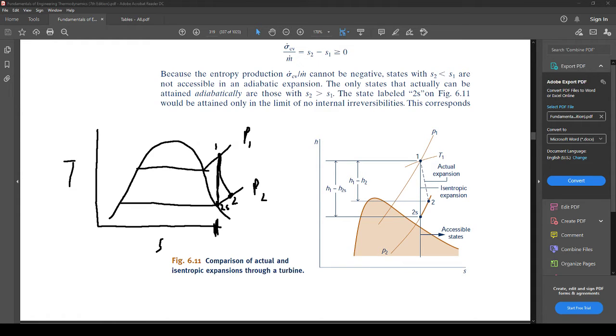So 2s means the isentropic. And by the way, anything with an S, so you could run into a compressor or a pump at states 3 to 4, and it's only after. There is no 1s, because 1 is a state going in always at these conditions. It's only after a turbine, compressor, pump, or a nozzle or a diffuser. Those are the only ones that have it, and it's always after.